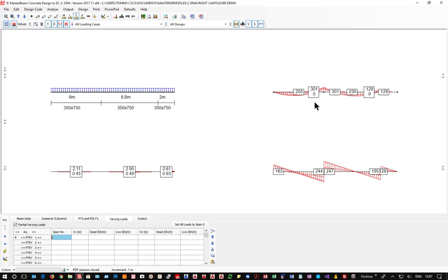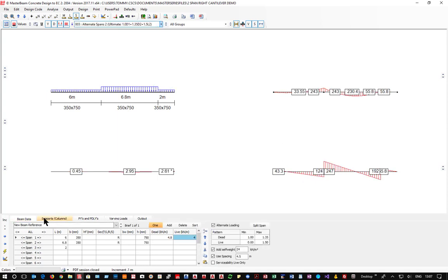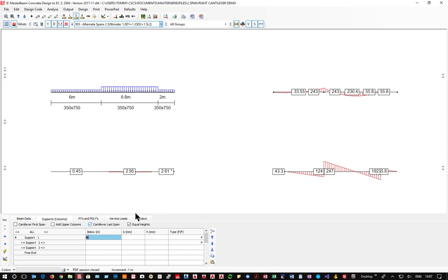So what can we see? We can see our bending moments, and we're looking at our different cases, and we can see our deflections over here as well for our different cases. Obviously we did tell it that the last span was a cantilever, so this is our cantilever. And let's just increase the scale of that, and you'll see that we are getting this small fixed value of moment due to the cantilever, whereas in this span we're just doing a straight hog between the two.